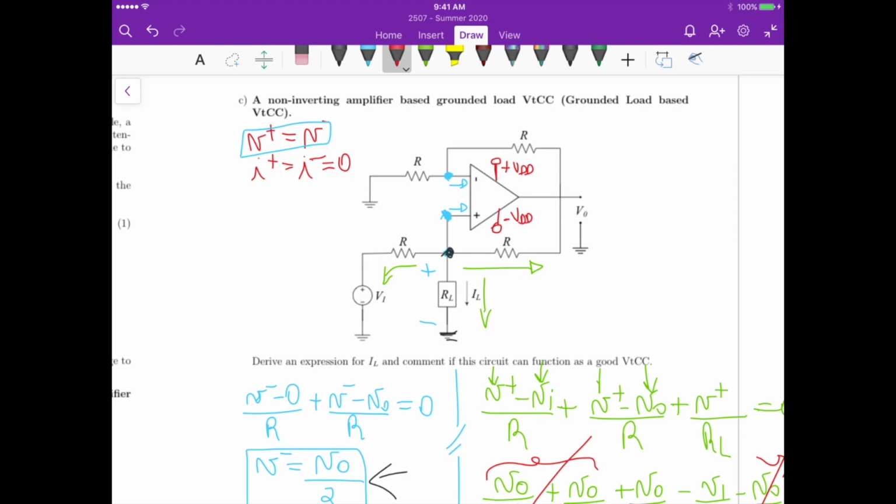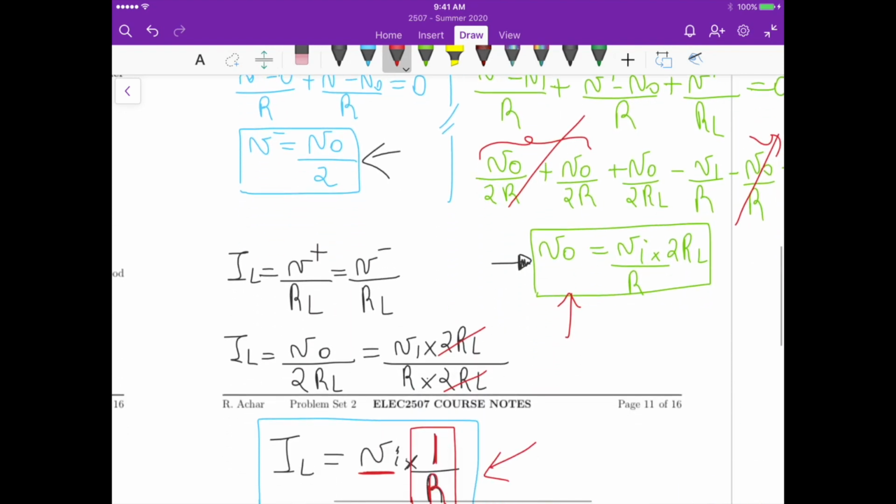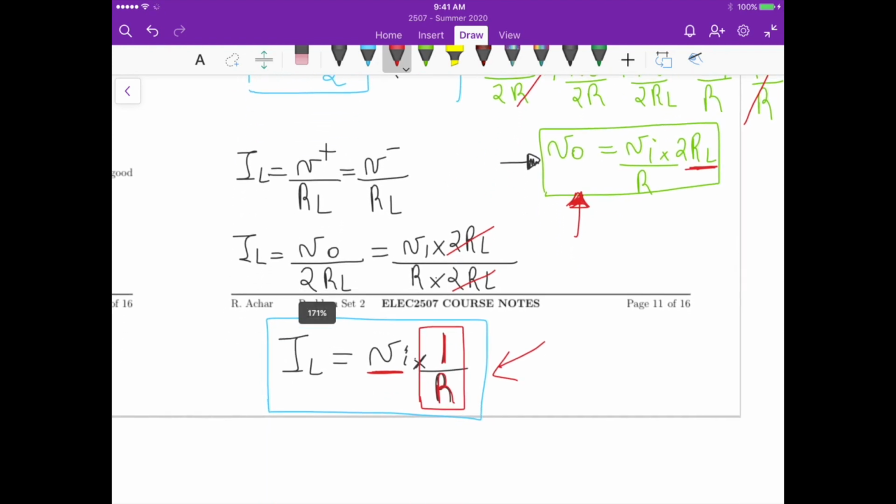Those are the maximum voltages that we can observe at the output of the operational amplifier. So if we use a very high value of RL here, we limit our voltage to something that is clipped by the maximum voltage that we are feeding.